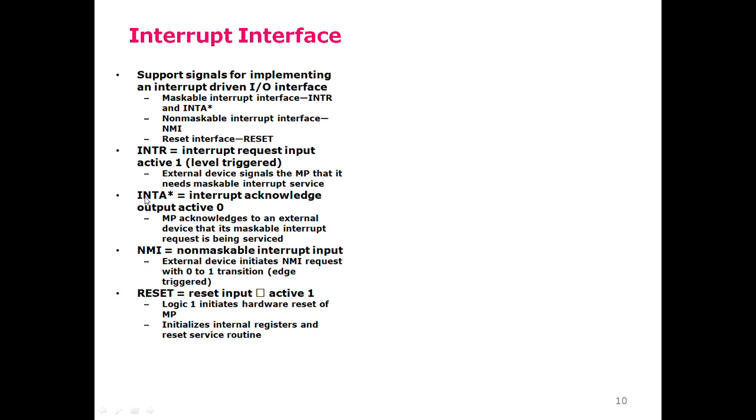When a 0 is sent through this pin, the microprocessor acknowledges to the external device that its maskable interrupt request is being serviced. When a request is received and an acknowledge is sent, the microprocessor enters an interrupt cycle, and an interrupt service routine, or interrupt handler, is executed to respond to that interrupt.